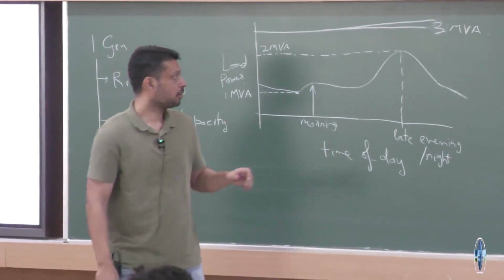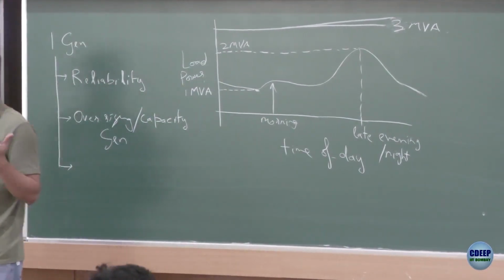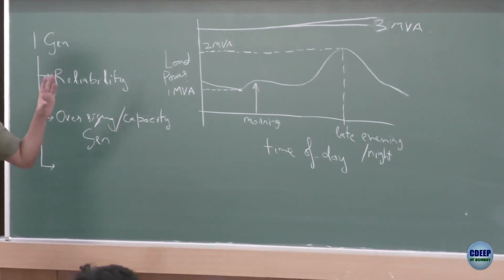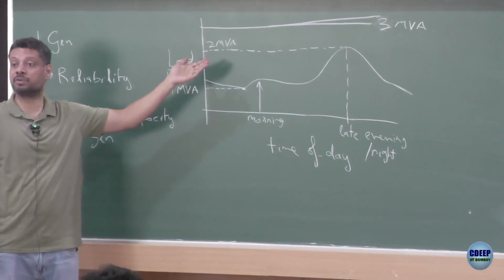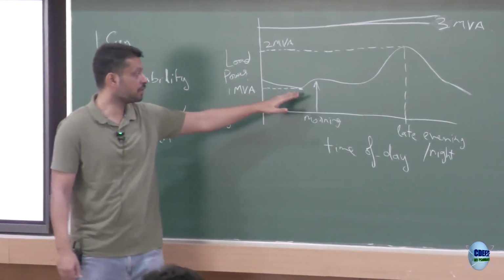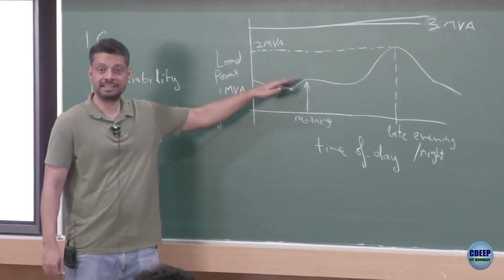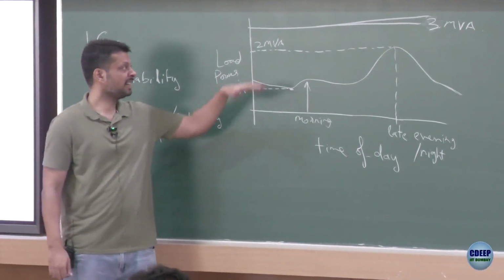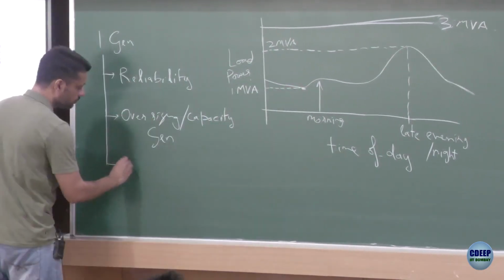So there is always a fixed power loss happening in these kinds of systems, and therefore they are much more inefficient if you are running at lower power as compared to higher power. So imagine if at this point you had only a 1 MVA generator, running that would have been much more efficient than running a 3 MVA generator to provide 1 megawatt of power, right.